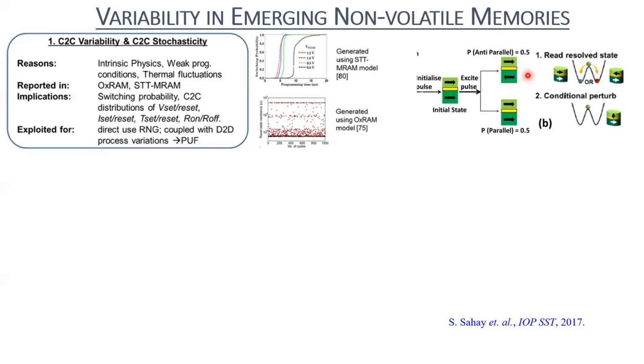Those electrons exert a spin transfer torque on this free layer, on the electrons present in this free layer, and they tend to rotate the effective polarization or effective moment of this free layer from this direction to this direction. So they tend to reverse it just by applying that torque. I mean, the charge current which flows through this spin layer gets spin polarized, because now the electrons will have their polarization or magnetic moments in the direction parallel to this spin layer.